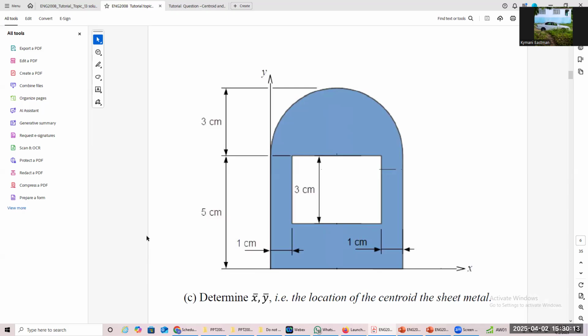Yes, I remember this, the semicircle and the rectangle. For the semicircle, you find y bar, it would have been 4r divided by 3 pi. Up at the center here, if you can see my pointer, up here, so you would have found that little distance up here. I can't write on it because it's a PDF. All right, so we are able to do that.